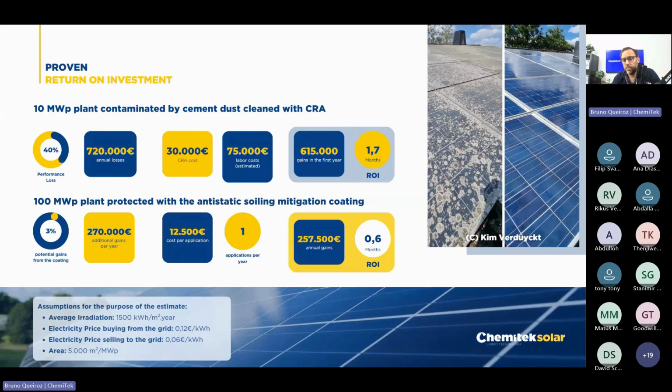It's the only way you can see the Solar Wash Protect leaving any type of stains, because the coating is transparent. You cannot see the coating itself after applying. So if there are any stains on the module, either the rinsing was not properly done, or the water is hard, and what you see on the modules after rinsing is the minerals that are left by the hard water. So those are the two cases where I see that stains can appear after using the Solar Wash Protect.